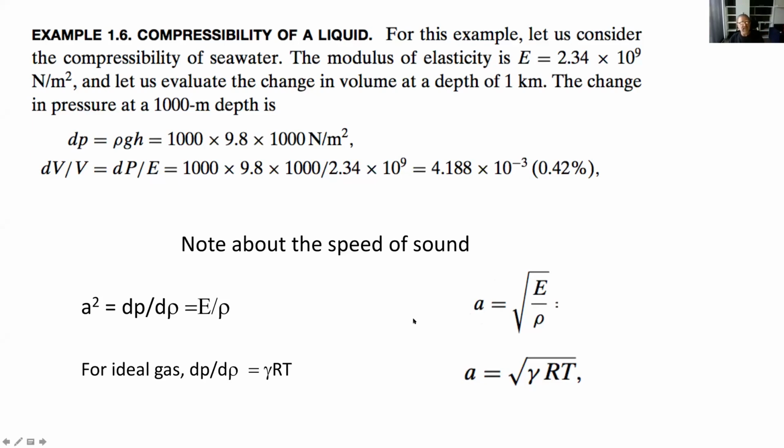When we talk about gases, it's more complicated, but we can take an ideal gas formula. Now, there is another assumption in the case of an ideal gas, that the compression of the gas due to the sound is isentropic, which means there are no losses. If there are no losses, again thermodynamics, you must have taken thermodynamics, so you love that, you show that dP d rho is gamma RT, therefore the speed of sound squared is gamma RT. Well, I'm taking it concurrently. I don't know if anyone else is taking it concurrently right now. I strongly suggest remembering these formulas. We're not going to deal with them too much, but it's a good thing to remember. Okay, for other cases, I'll have an example in a minute.